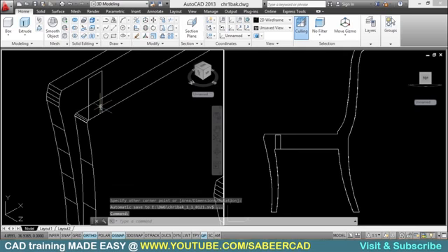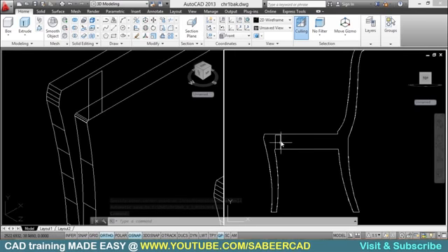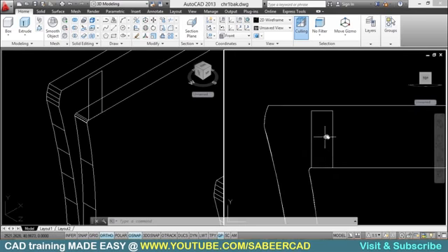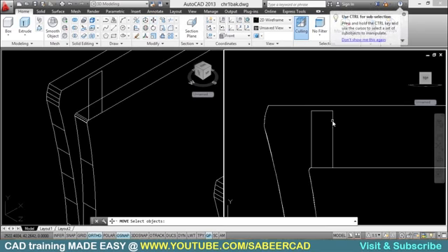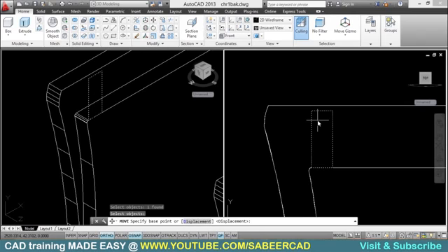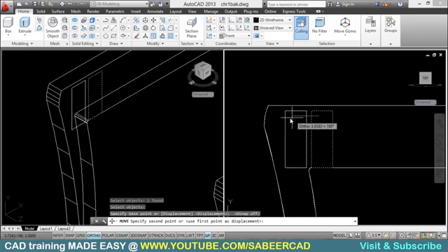Now you can see the rectangle on the front elevation. Over here, you can position the rectangle properly. So I'll go to the move tool and select this profile, and when I'm asked to specify the base point, just turn off the O snap by pressing the F3 function key. Okay, you can turn off the object snapping. Now click the base point over here.